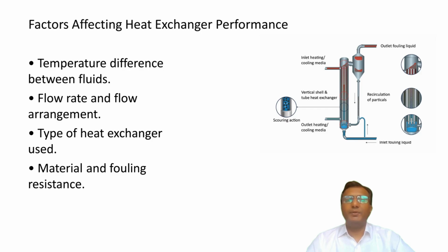Several factors influence heat exchanger performance. The temperature difference between the fluids drives heat transfer, with larger differences increasing the rate as per Newton's law of cooling. Flow rate affects performance. Higher rates enhance convective heat transfer, but may require more energy for pumping. Flow arrangement impacts efficiency, with counterflow being the most effective due to sustained temperature gradients.